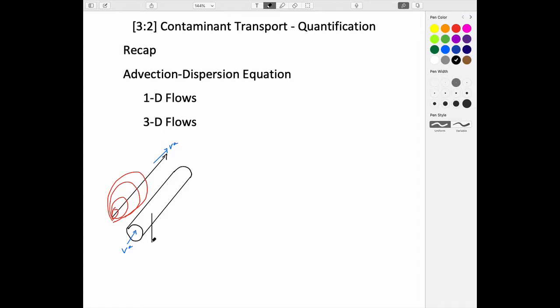and that we could use that to look at, if we wanted to, what the longitudinal profile would be in this x direction, downstream direction, in terms of concentration gradient. I'm not sure what colors we used. I'm going to use green. C over C0, which would range between 0 and 1. And physically, what we've looked at before is that this would look something like plug flow if there was no dispersion.